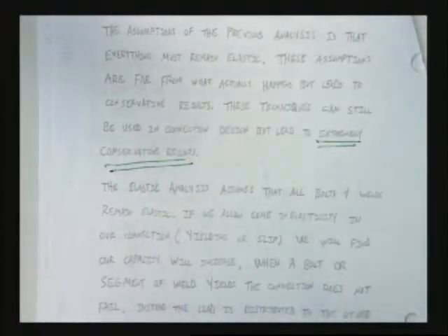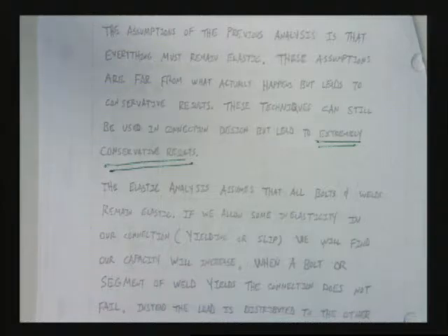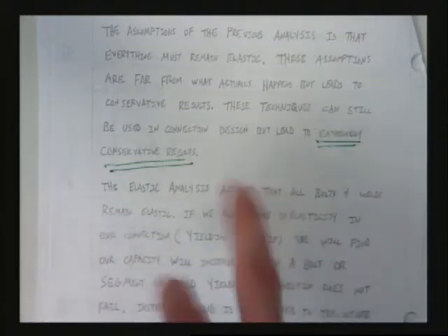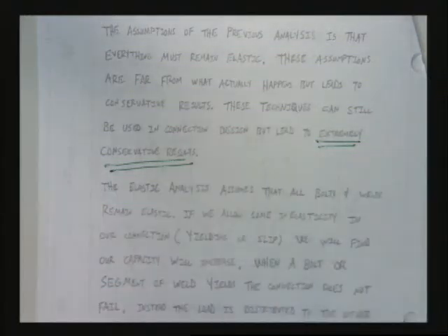Okay? So when we were out on our field trip, Scott Ambrose said, do you teach them the unified force method? Okay, and he used a different term than I'm used to using. But he's basically asking, do you teach them this inelastic connection design technique? And the answer is yes, we do teach you that. He's talking about how the elastic was very hard and yielded very, very conservative connections, and the inelastic gets you more accurate, less conservative, but it's accurate, so it performs well.